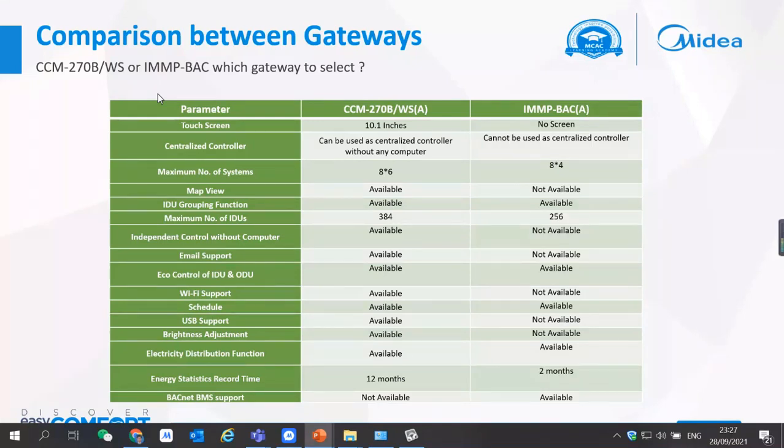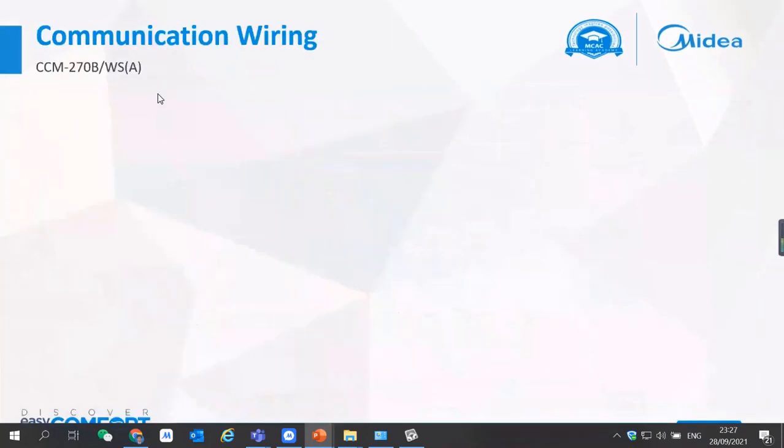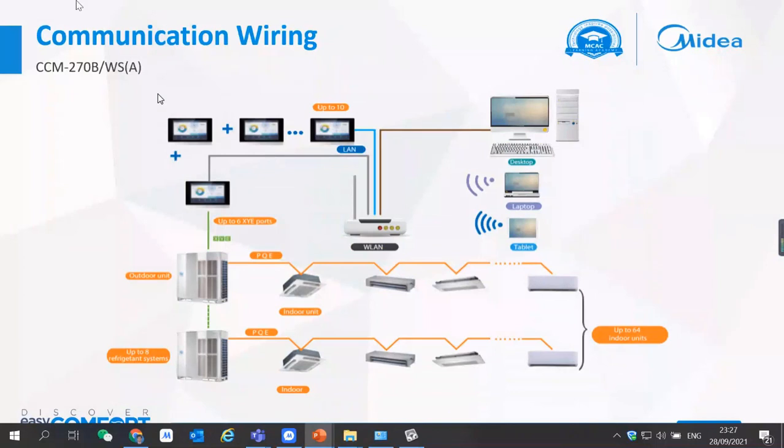Energy statistics record time. In the beginning of the presentation, I said, what is the motto of Immpro? Energy consumption division, right? So if we look at our setup again, this 10.1 is connected through a LAN cable to this router, and from this router it is connected to the Immpro. It is very possible that someday this LAN cable is loose. So data is not going outside from 10.1. It is storing inside the 10.1 now. Unless you find out, you never know when you visit this project site.